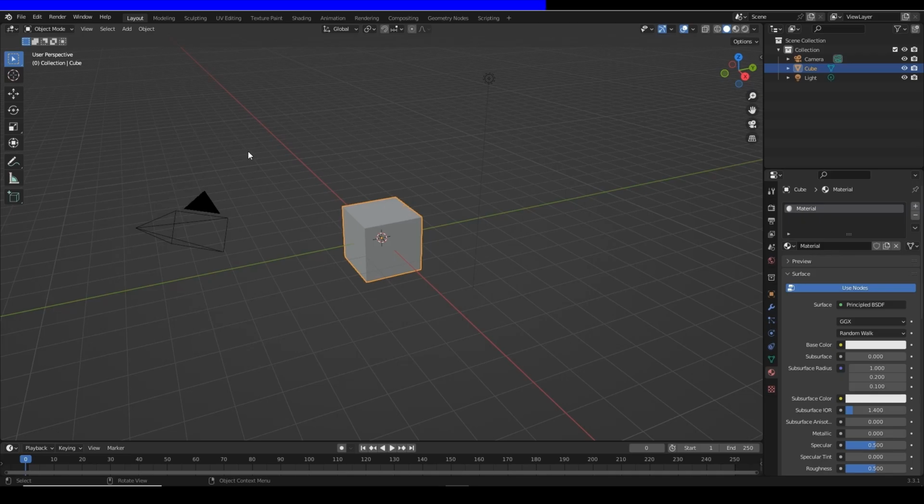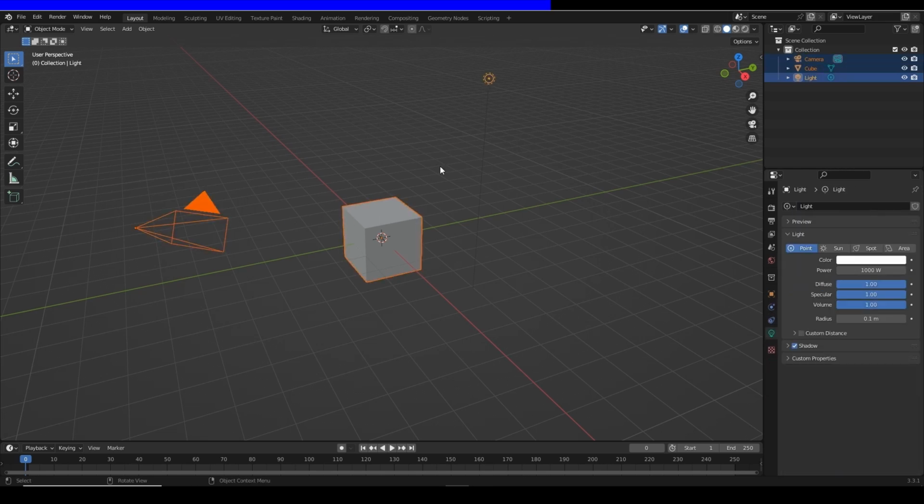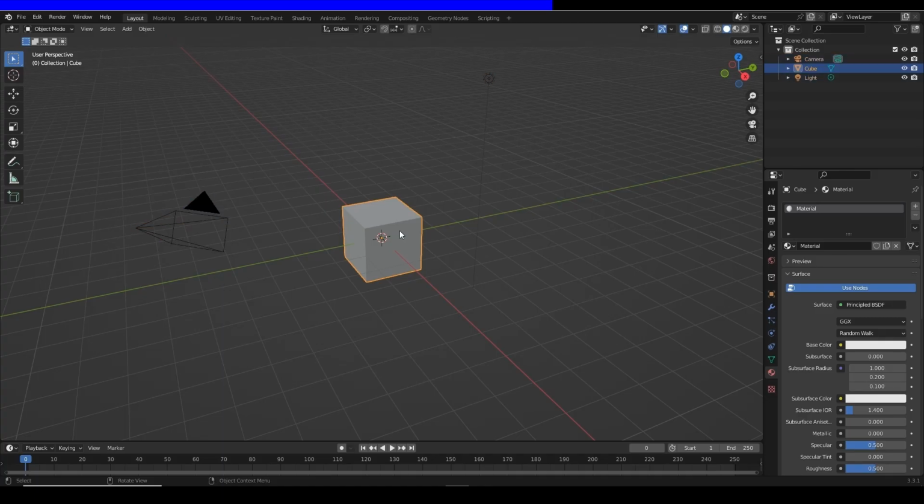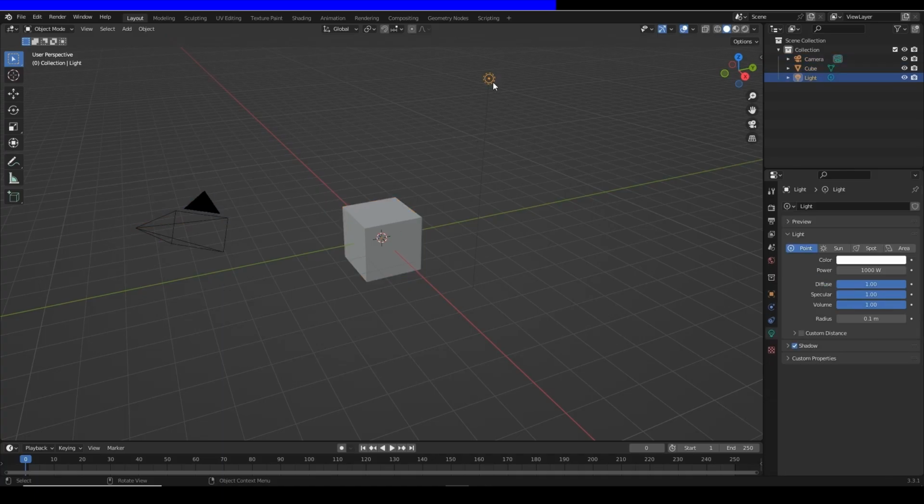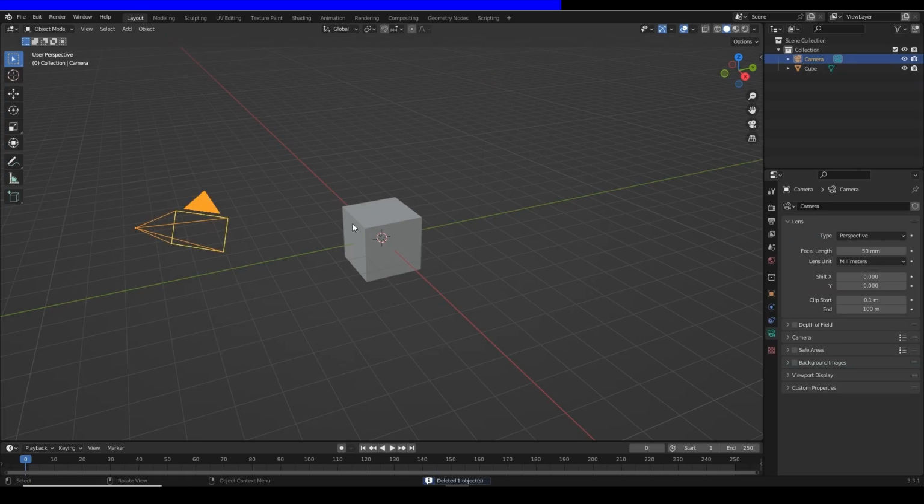We select objects by left-clicking them. Shift selects multiple objects. A selects everything. We can remove objects by selecting them and then pressing Delete. Typically, it is a good idea to remove the camera and the light supplied by the template so that we can focus on our model.